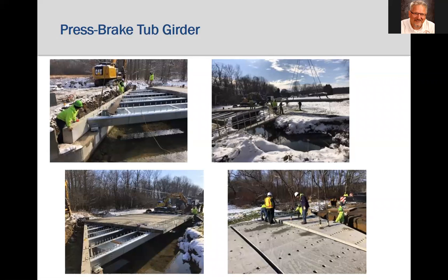in one day. Then, over the next week, the shear stud pockets in the precast concrete deck panels and the transverse deck joints between the precast concrete deck panels were filled with high-strength polymer concrete. The concrete curbs were then cast and the steel guide rails were installed on top of the concrete curbs.